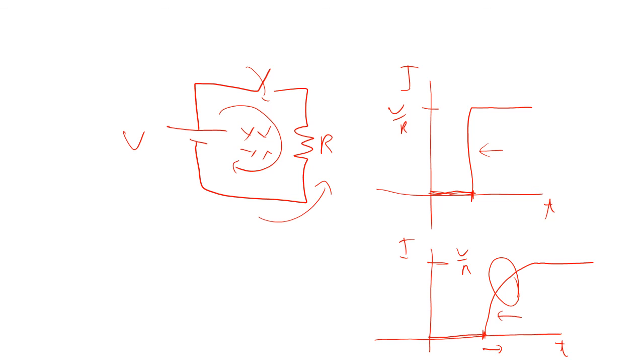Every circuit is going to have a response time when you turn it on or when you turn it off, because there's always going to be a little bit of inductance. They will never instantaneously become whatever it is that you wanted them to become. How much response time depends highly on the amount of inductance, because the time constant is related to the inductance of the circuit divided by the resistance in the circuit.